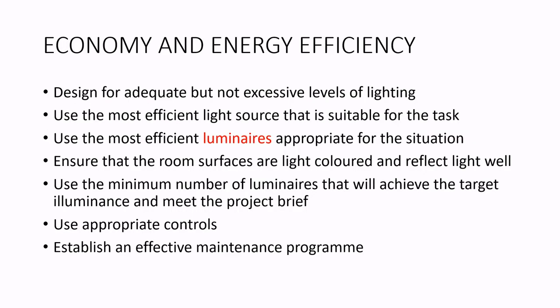Now we come to economy and energy efficiency. When you are doing a design, you have to do that design economically. So you should not over design your lighting system. You have to have adequate lighting levels but not excessive levels, and you have to make sure you are using the most efficient light source available, and that should be suitable for the task also. There are some light sources that are not suitable for some tasks, so you have to avoid those and use the most efficient and the most suitable light source.